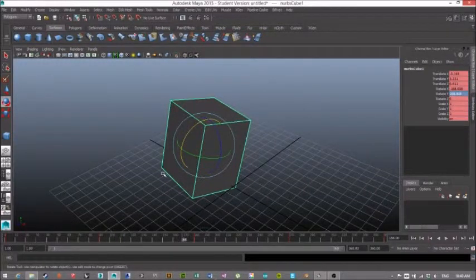But when you batch render, you're going to output a whole bunch of images. So we have a 360 frame animation here. If we were to batch render this, we would be outputting 360 single images. These single images now need to be composited into a movie, and you can either do it in QuickTime or Photoshop.